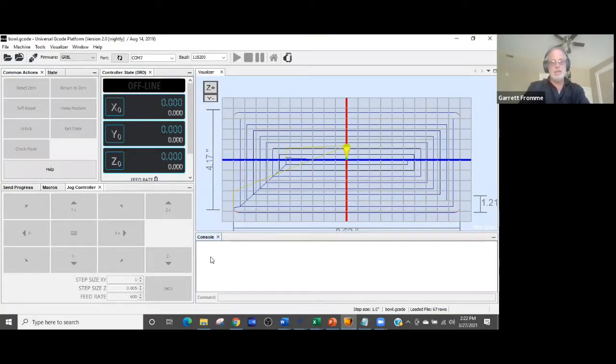And then you can send your machine home and do whatever you have to do to fix the problem, and then tell the router to go back to that line number. That's a little more advanced because then you have to edit your G-code to make sure it gets there in the right way. If you ever run into that, I'll be happy to help you out.